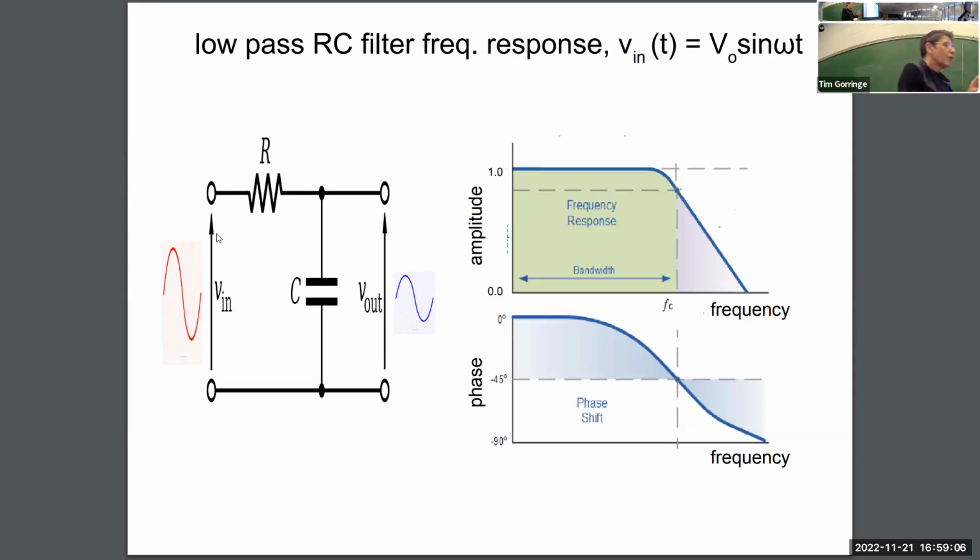So what I just showed you for the high pass filter and the low pass filter was what we call the step response. That's one way of characterizing the filters. So I applied a voltage step from 0 volts to V0 at the input of the low pass filter, or the input of the high pass filter, and we saw the response at the output of the high pass filter and the low pass filter. And we saw that they were quite different responses.